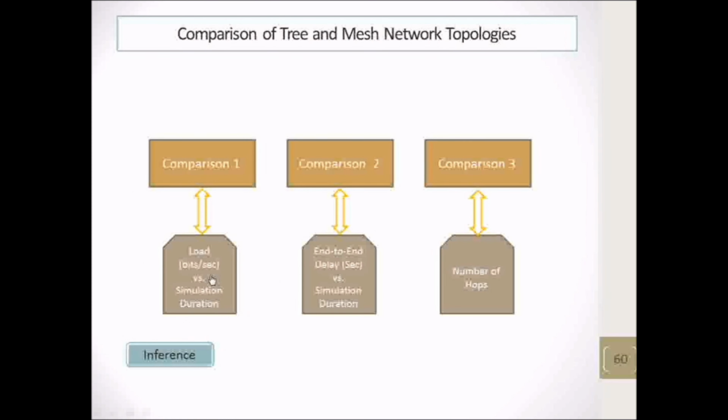With respect to these signals, the LabVIEW server front panel is built. The front panel consists of various sections. First, this panel has switching controls. The temperature sensor is always on because that is the main application of the project, and the rain sensor and pressure sensor have on and off switches. We can switch off the rain sensor and pressure sensor in case we have to save power, and for that we are using relays.